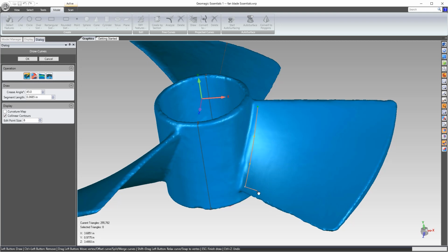So speaking of that, if I just come over here and start drawing, I can create another spline and then hit Escape. And then again, you can always come back and manipulate the curves and move them around. So a red node is an endpoint that divides up multiple splines. Essentially, if a spline has all orange dots, it's all one spline. And then a red node like that means that's the beginning and end of a spline.